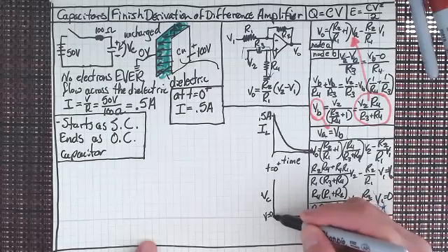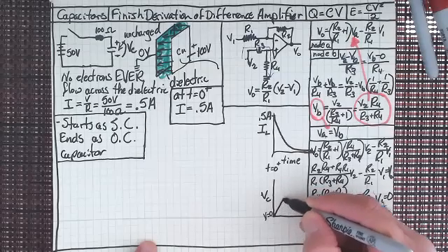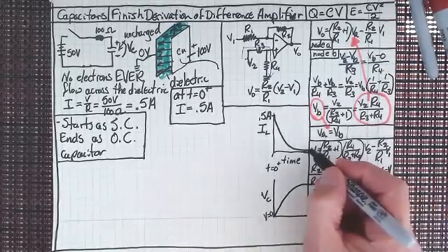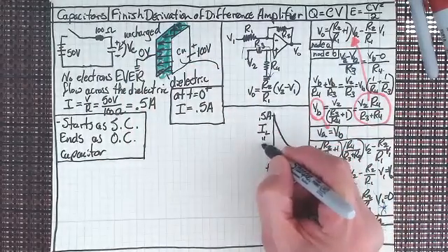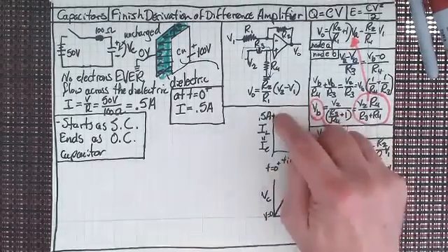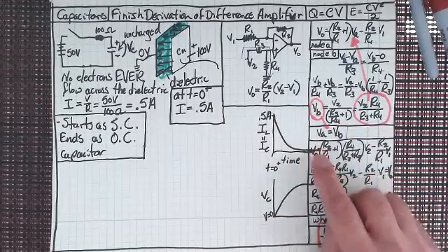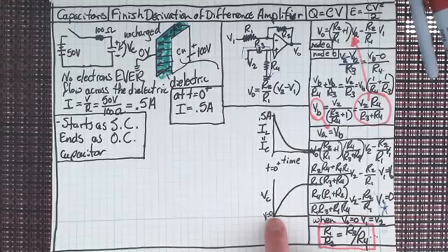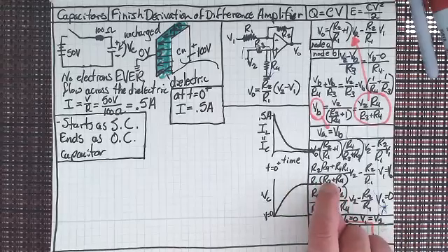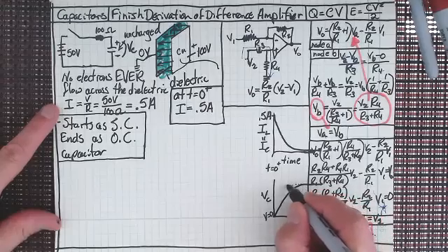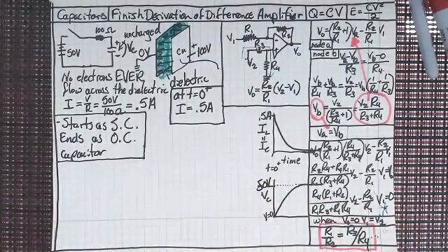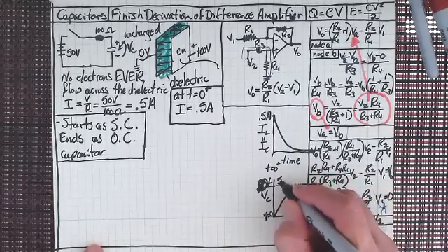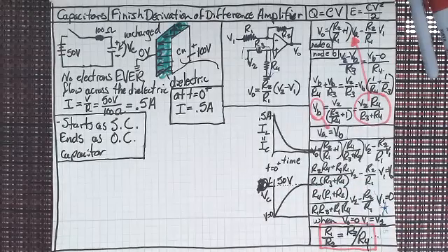It's going to start down there at V equals 0, and then it's going to asymptote off at a certain level, right? So the line current, which is equal to the current going through the capacitor, is going to start off as a short circuit and go to an open circuit. The voltage, on the other hand, starts at zero and goes up. What is that voltage that it's going to asymptote out at? It's going to asymptote out at 50 volts, isn't it? That's a 50. 50 volts, because eventually it's going to be an open circuit. Put a star next to that.